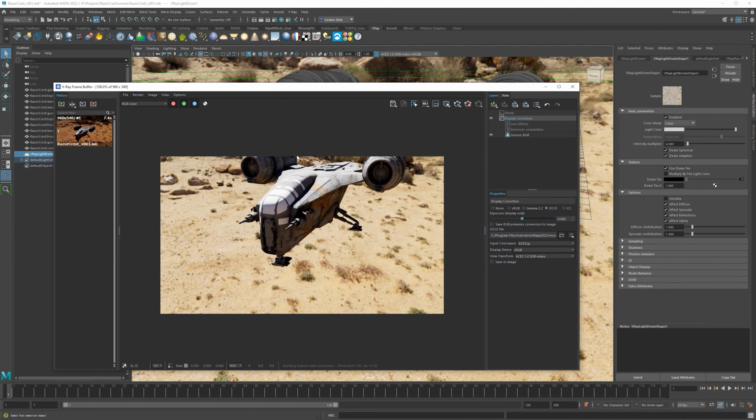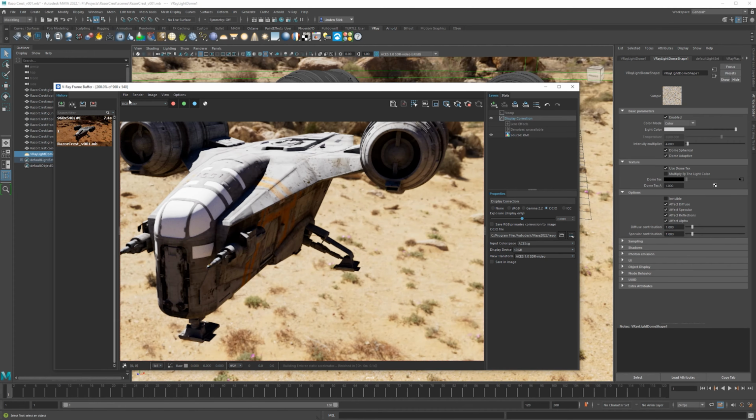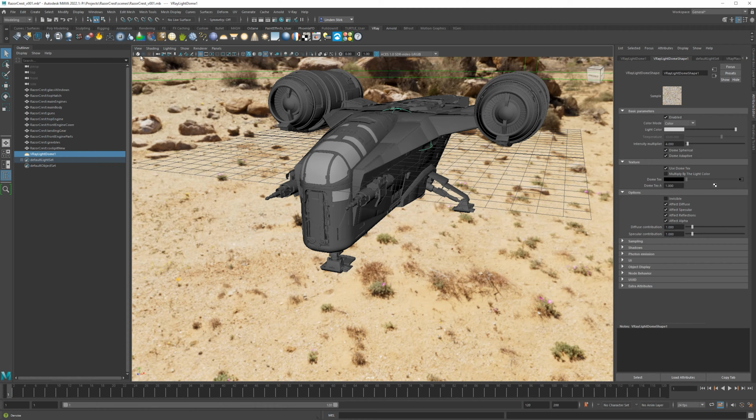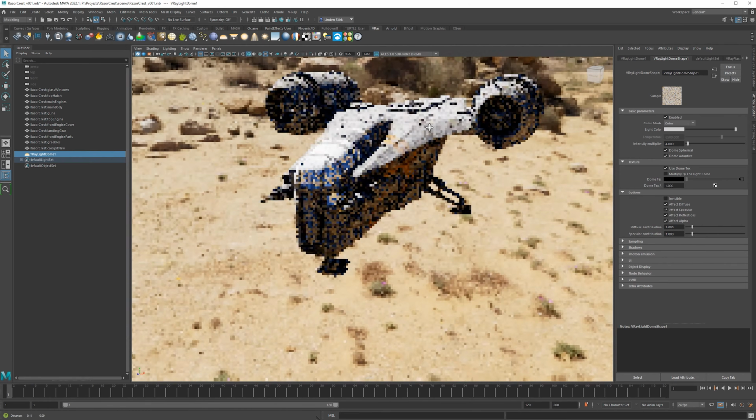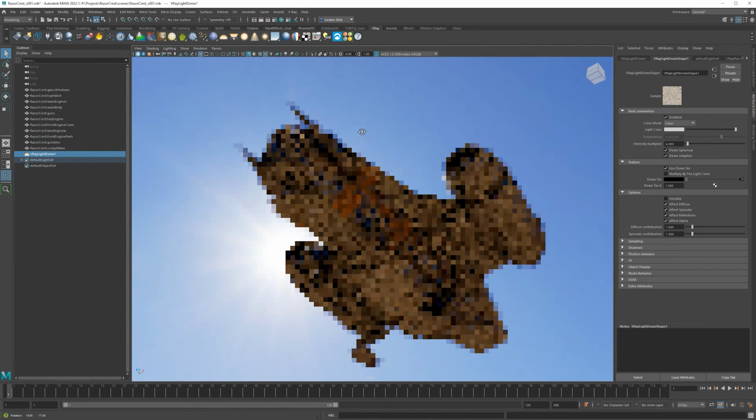So for this next part, I find it a little bit cumbersome to have the V-Ray VFB open. So I'm going to just stop this. If you have trouble with this next part, go back to just using this. This is good. But we're going to do it in the viewport for a lot of this lecture. So I'm going to click on the little V icon here. This is going to basically do the same thing, but in the viewport where we can navigate around.